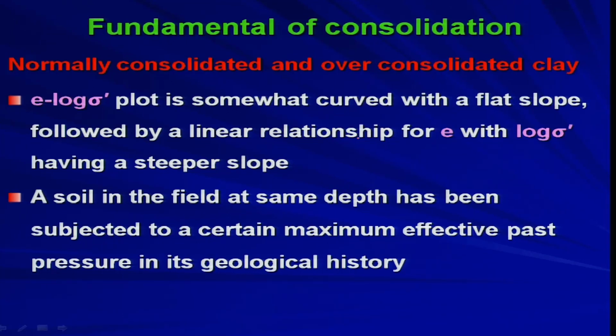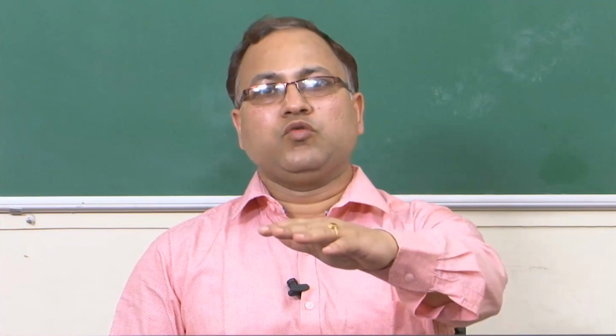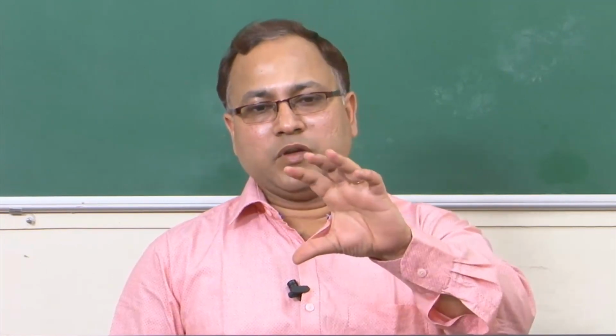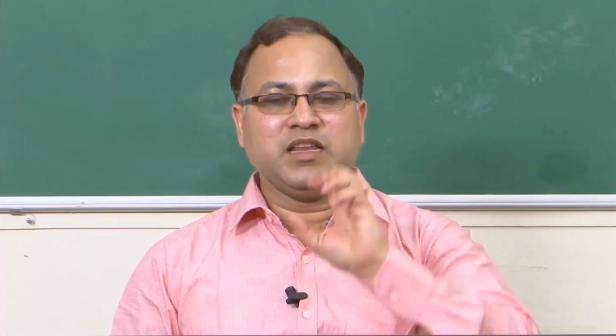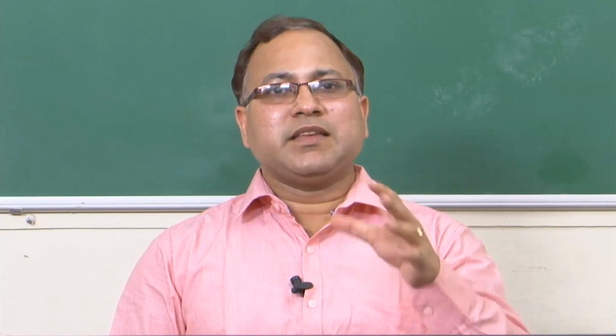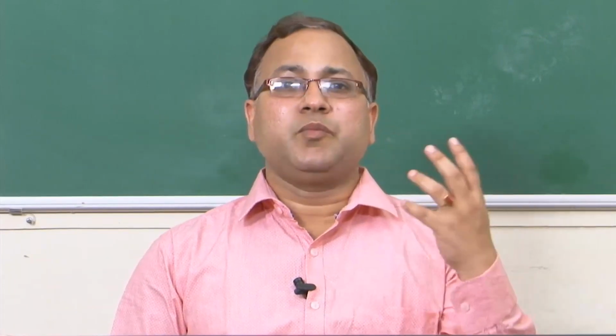Please try to understand, it is very conceptual. A soil in the field at some depth has been subjected to a certain maximum effective past pressure in its geological history. What does it mean? Suppose you have some soil deposit, and if you go to some depth and consider a soil block or soil element, that soil element has already experienced some previous pressure, the pressure history or stress history.